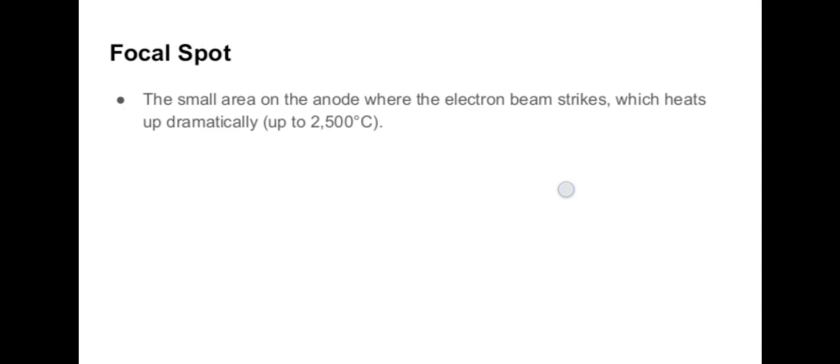The life of the rotating anode X-ray tube is limited because of pitting due to the continuous electron bombardment on the anode surface. These changes are due to thermal stress, and this pitting reduces the X-ray yield and changes the spectral distribution. The decreased output results in excessive scattering of X-rays and increased absorption of X-rays by the target itself. A pitted anode will affect the electric field between the cathode and anode and so alter the size of the focal spot.